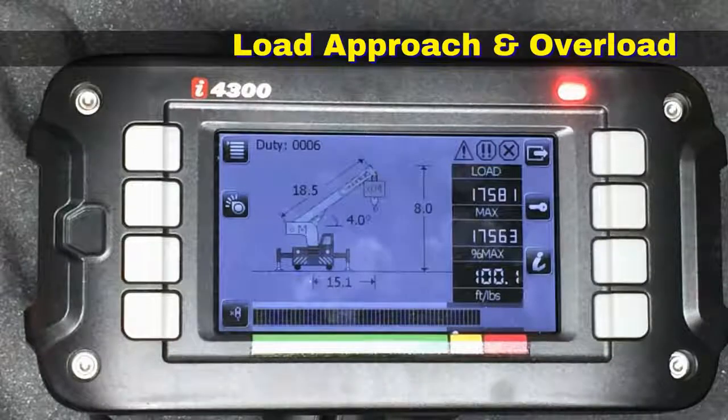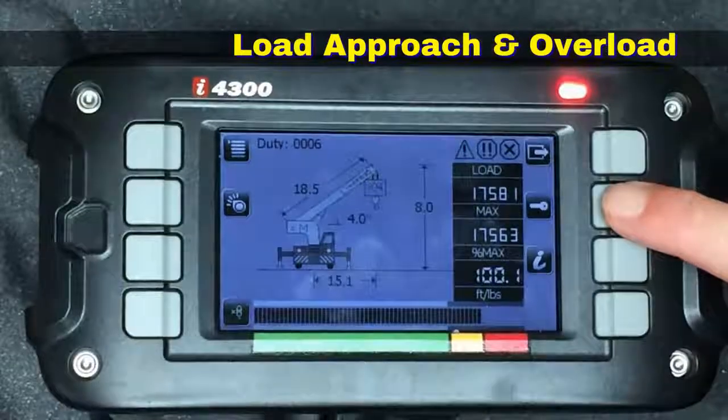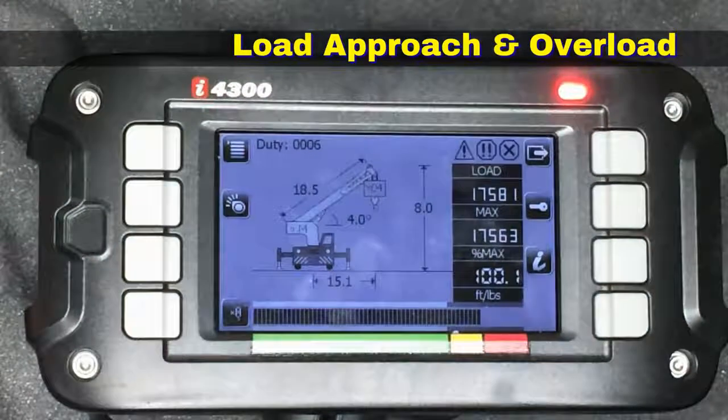If you need to continue winching up or booming down or telescoping out, you can override the current situation by pushing the button next to the key symbol. Pushing the button will allow you 8 to 10 seconds worth of override. After that, the lockout condition will be reinstated.